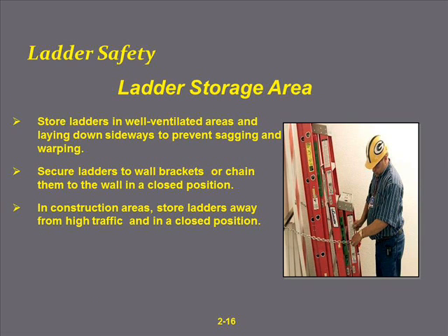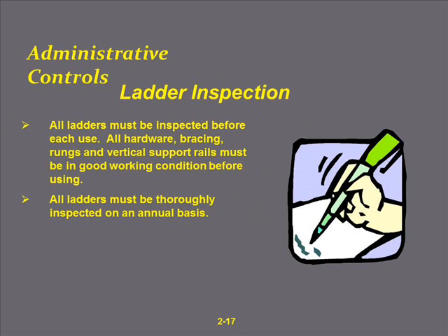When you're done using your ladders, make sure you store them in a well-ventilated area, laying down sideways to prevent sagging and warping. Secure ladders to wall brackets or chain them to the wall in a closed position. In construction areas, store ladders away from high traffic and in the closed position. Ladder inspection. All ladders must be inspected before each use. All hardware, bracing, rungs, vertical support rails must be in good working condition before using. All ladders must be thoroughly inspected on an annual basis as well.